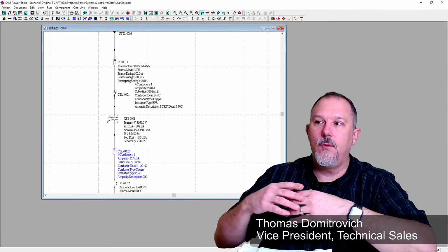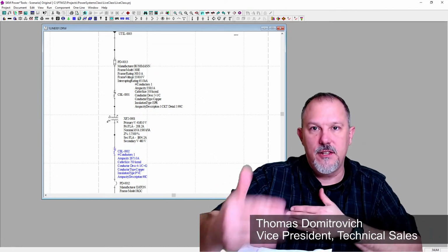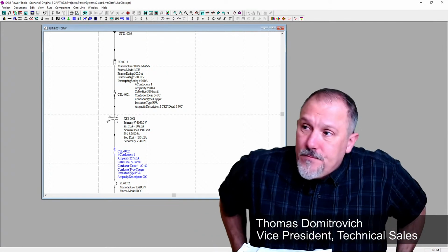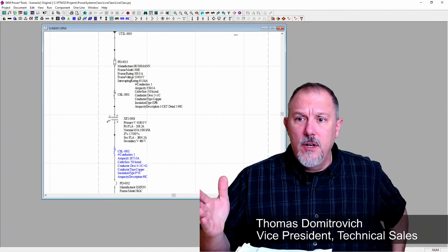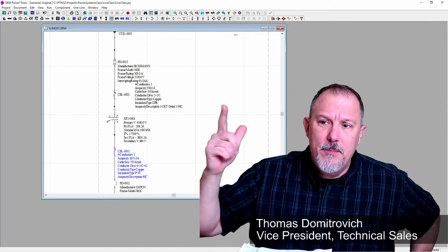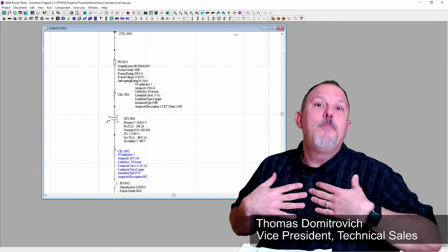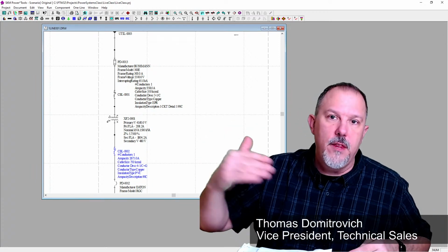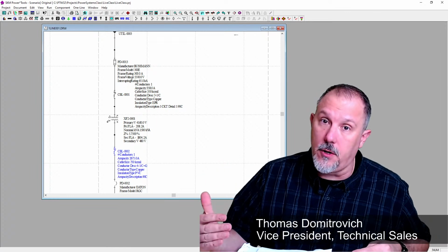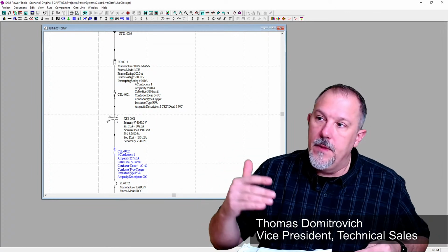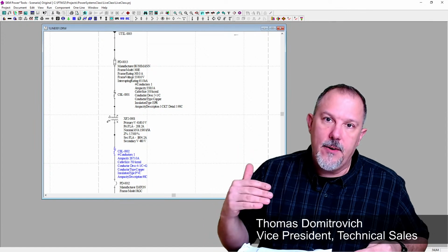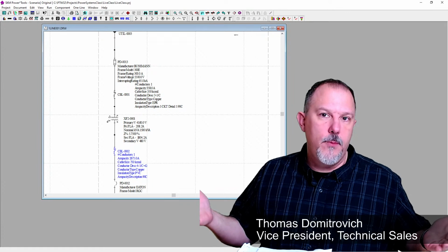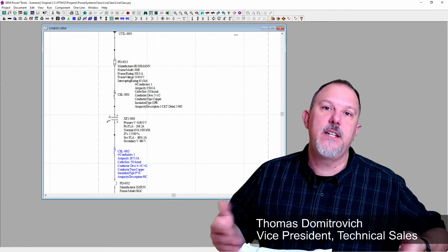And the first step is to establish the size of the overcurrent devices. This is the way I do it. With a transformer, that primary is overcurrent protected. Now the secondary device, I put the panel board I want on it. Okay, I know I can go greater than the full load amps of the transformer because I can push it hard if I want to. But for the secondary, I can establish what the size panel board is. If it's an 800 amp panel board, I put an 800 amp overcurrent protective device, I'm golden.